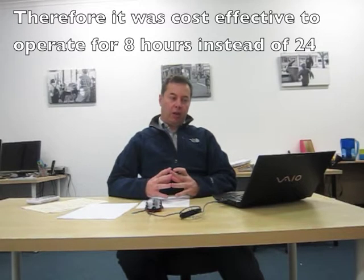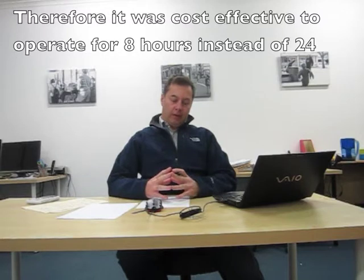So we established through the energy modelling that by insulating the roof and by introducing an optimal ventilation rate, operating this ventilation for 8 to practically say 10 hours a day would be sufficient to cool the building by 5 degrees compared to the existing building.